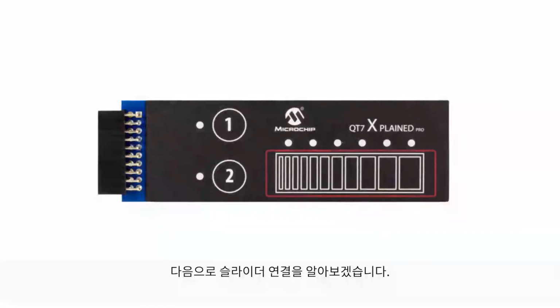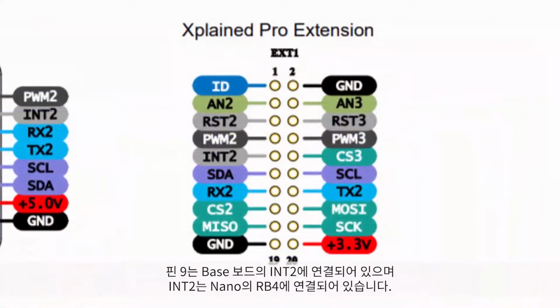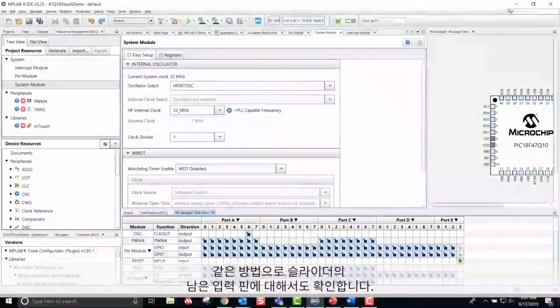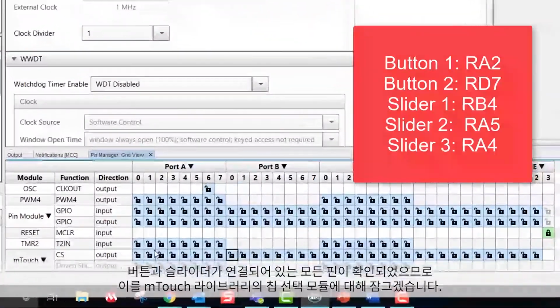Next, I need to find the connections for the slider. Segment 1 of the slider connects to pin 9 of the Explain header. Pin 9 is connected to INT2 of the baseboard, which connects to RB4 of the Nano. I'll use the same technique to figure out the rest of the slider input pins. Now that I know all of the pins that our buttons and slider are connected to, I will go ahead and lock them to the chip select module of the mTouch library.